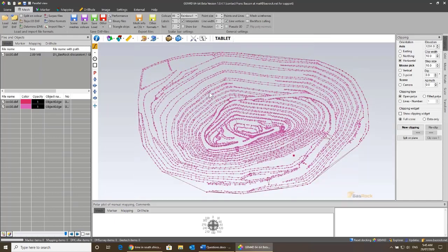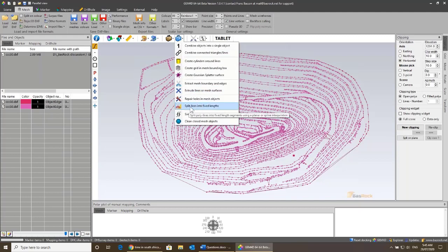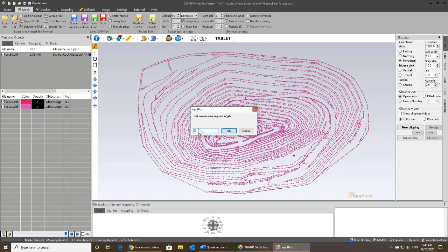And you can see your vertices are not always well spaced. They're sometimes far apart, sometimes close apart. So I want to make that more uniform. So I'll go for a process that says split the lines into fixed lengths. So yes, I want to split them into fixed lengths. I want to create myself a point and you decide the number in terms of what your resolution should be. I want to do it every 5 meters. This is a stiffness number.